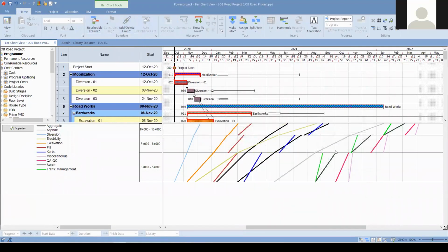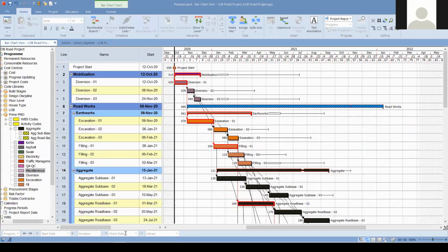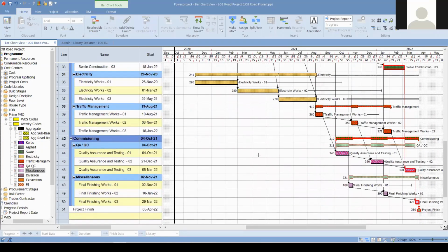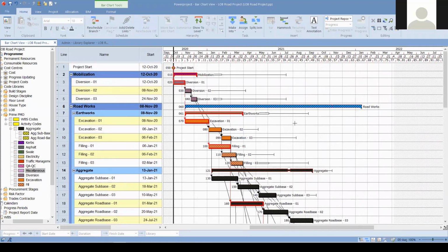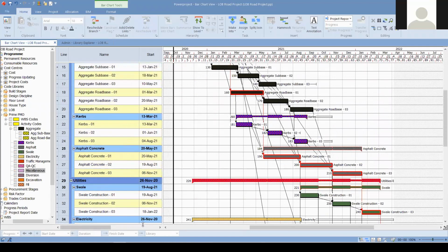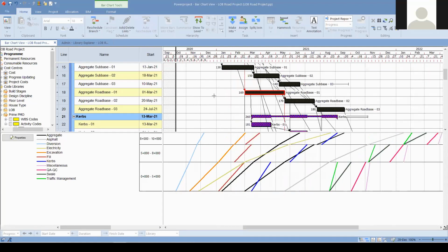Okay, so we have some changes, and then we can focus on all the project scope, because in this Gantt view you see that we are able to scroll down and we only have 50 activities. As you may know, all the project schedules have thousands of activities. So controlling all the scope with this Gantt chart will be a suffering issue. However, with this single view of representation of these activities, where they are located, when they will be active in progress, or when they will be finished, we will be able to track with these line of balance diagrams.